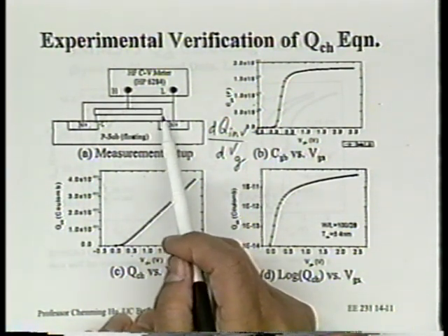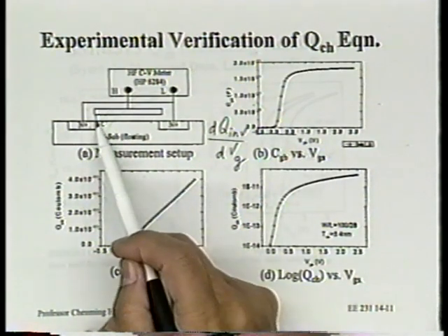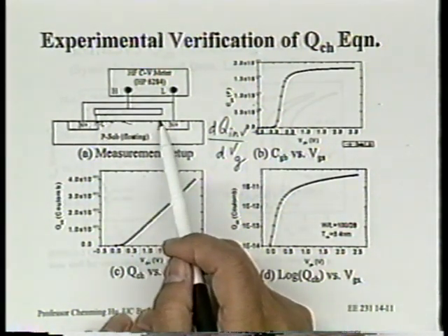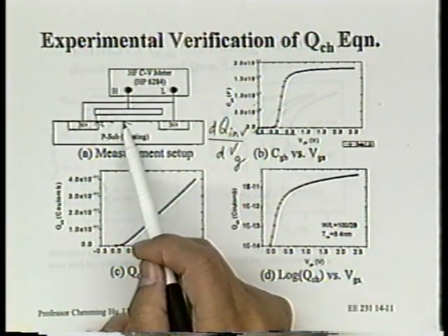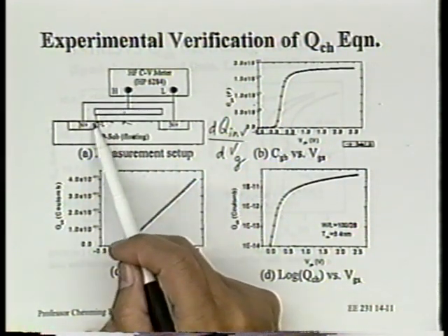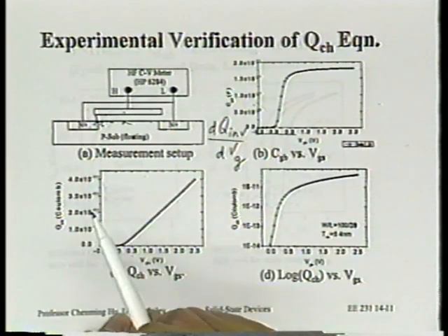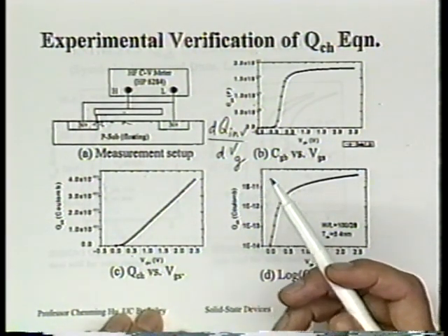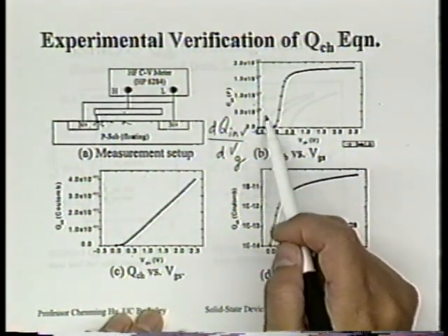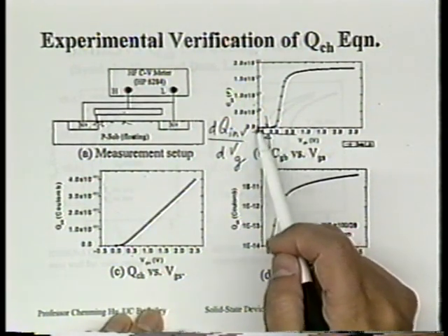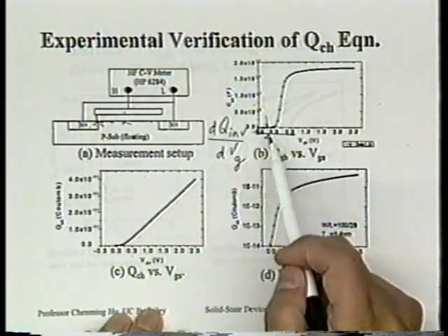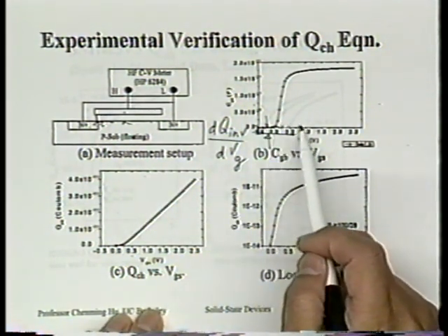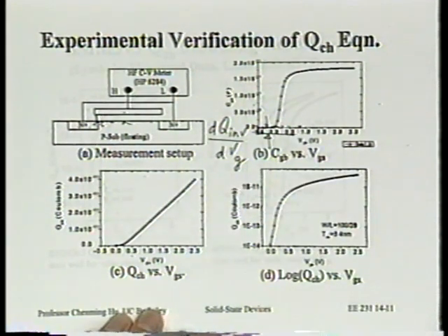In strong inversion, you see the entire channel. In the depletion or the accumulation region, the capacitance between the gate and the source/drain is only the overlap capacitance. So that little value you eventually see is the overlap capacitance. So you just set your 0 at this point, then you know your real channel capacitance. Is it okay?